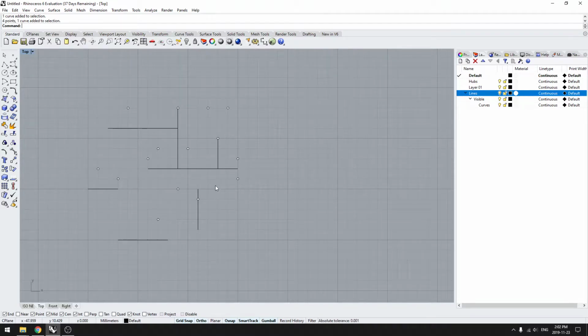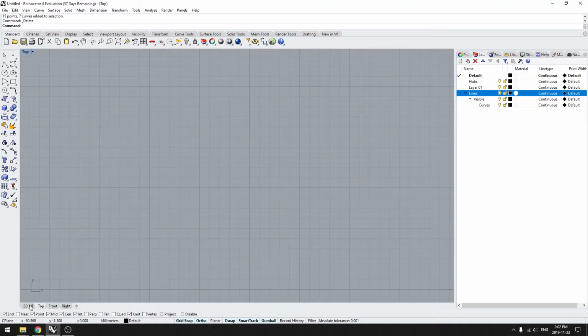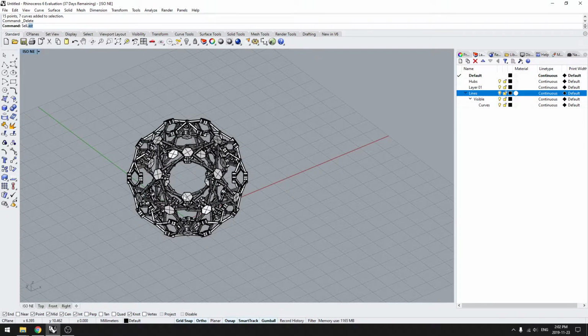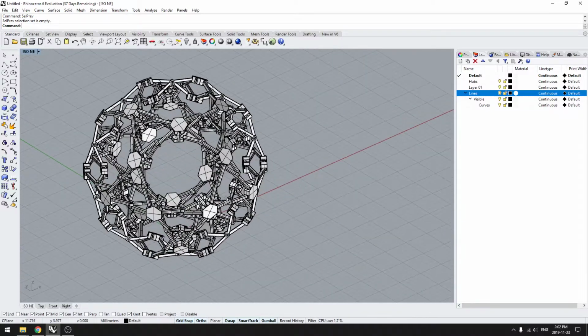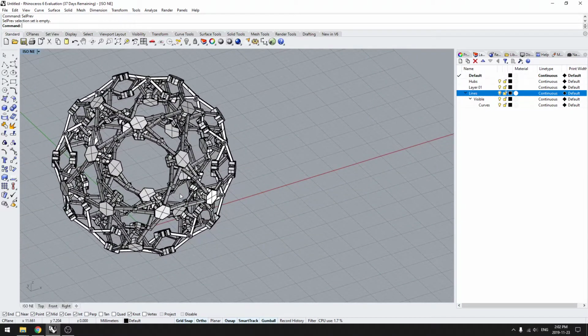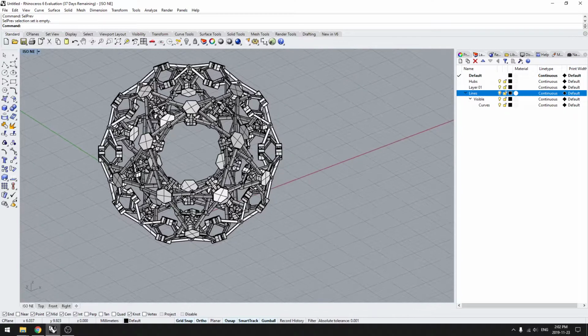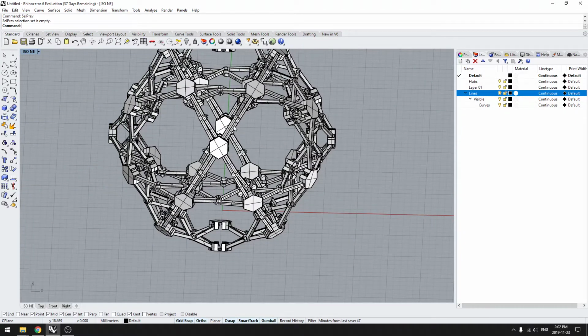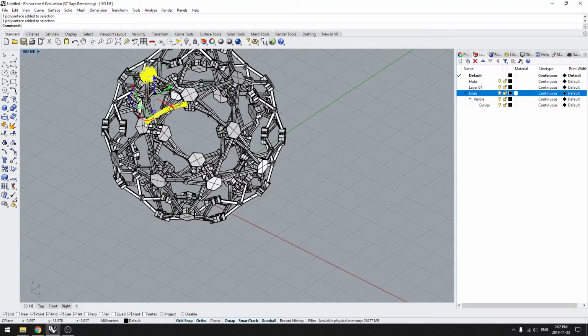You can also do a really good command. This is a really useful command actually. It's select last, and there's also select previous. What these commands do is they select objects that you were working with before, but there's a key difference. So if I were to do select last, let's say I have a couple of these objects, right?